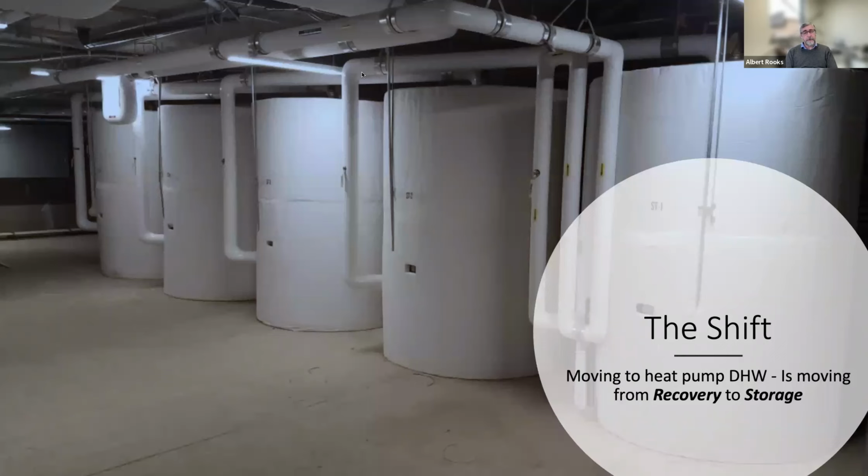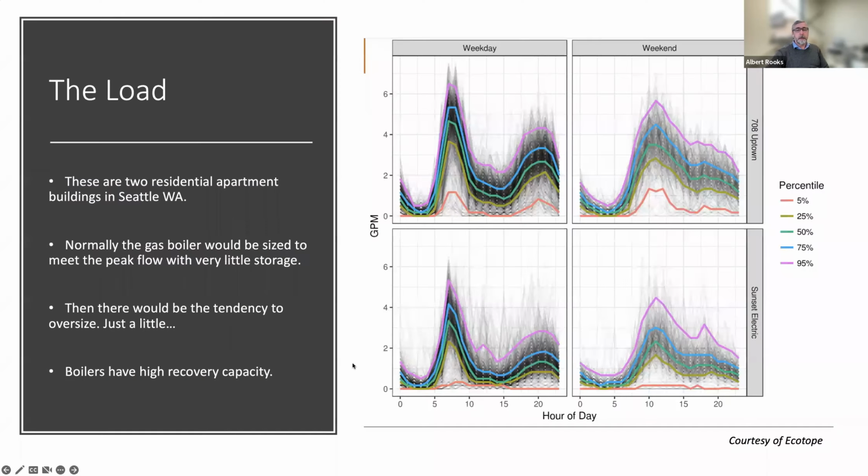The biggest difference with heat pumps is that they have a much slower recovery rate. So the design strategy is to step back, understand the building, and use storage, building that storage in advance, and then give it to the building as the load comes out. So it's really all about understanding the load, and one of the best loads we understand right now is multifamily residential, and workforce or retirement housing, with their various load patterns.